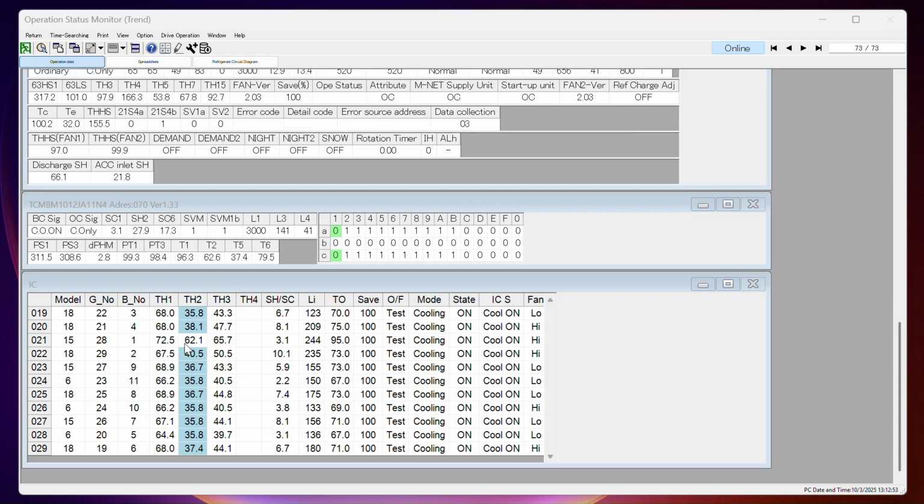All right, as we can see, we lost refrigerant on address 21, branch number 1, and we closed branch number 1, so that one is correct. Now we would continue on, if we were doing a full port verification, we would continue on through this whole process in order to make sure every port was correct.